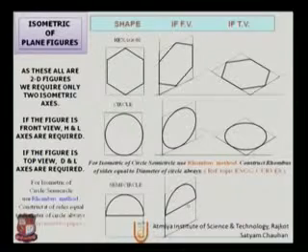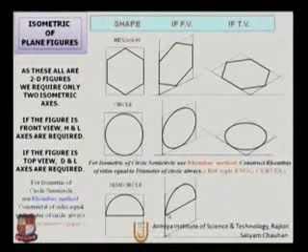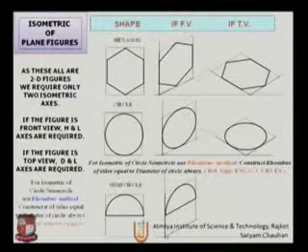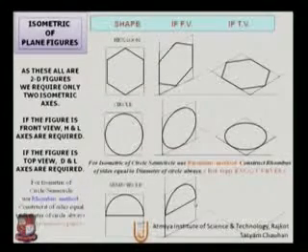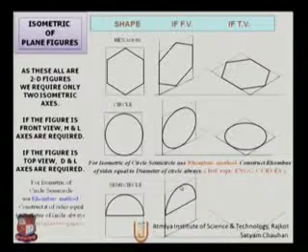We don't need to produce, we need to take from here to this midpoint and this midpoint, simply join an arc, and from the other end to get the center point, we need to join here and the other midpoint to join the smaller arc to produce the smaller radius.